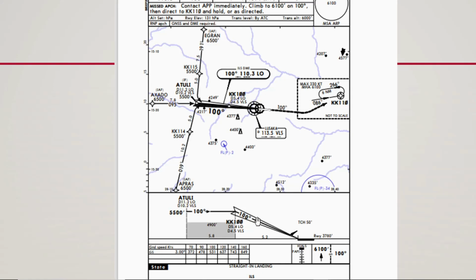We will also show what will happen if we came, let's say, from this particular point here and dip down, and we'll also show what will happen if we go a bit further out and then we come back this way and intercept the glide slope from below. So what you want to appreciate here is how your instruments will be looking depending on where you are.